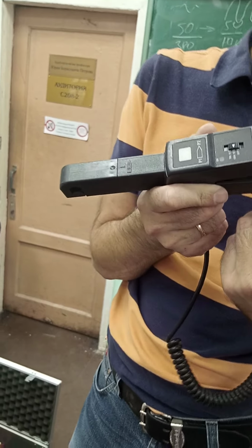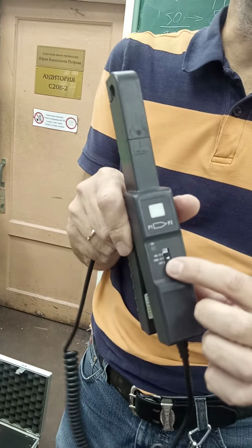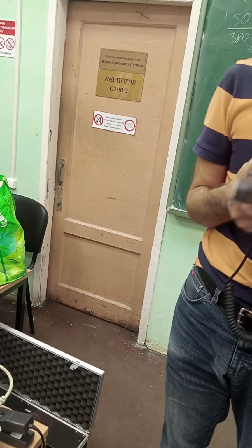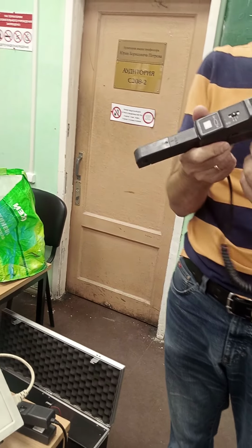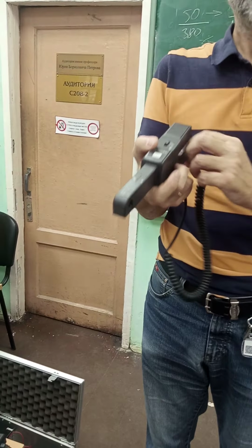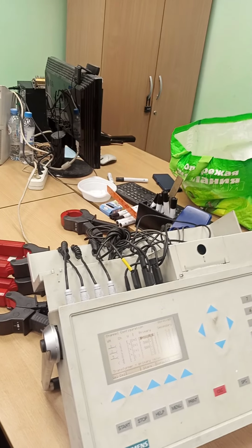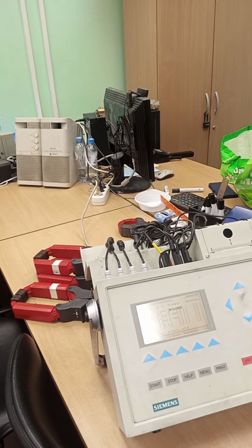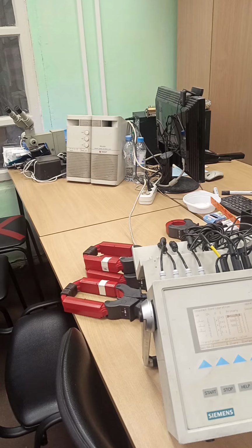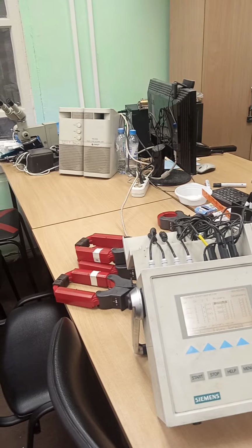Yeah. Primary, secondary on both of them. But why do we have two different transformer ratios here? Because this clamp has two different ranges. Okay. 10 ampere. For 10 and for 100 amperes. Yes, we have two different ranges, and of course we need to use the proper range because otherwise we can get measured values 10 times more or 10 times less than we need. Okay. So we can take incorrect values. So I told that this is the main characteristics of clamps, and it should be entered carefully.